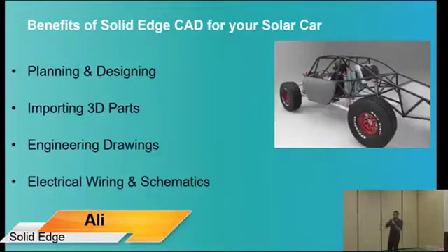Thank you. So as Kyle said, we have a technology here, Synchronous Technology, unique to Solid Edge. There are no other CAD software out there that can do this. What I like to call it is history-free modeling as opposed to history-based. And the CAD software that some of you mentioned, Fusion 360, SolidWorks, is all history-based, which means you start with a base feature, you start a sketch, you make a feature, and then you build on top of it, build on top of it, build on top of it.